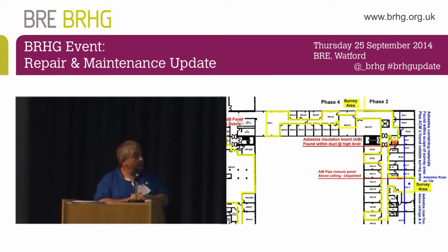And the requirement is, wherever you're doing building and maintenance works, that you do a refurb and demolition survey. That's much more intrusive than a management survey. And we have to make sure the client's aware of that, because they say, well, we're going to open up the ceilings. Well, hang on, Dave, they're all brand new ceilings. I said, well, do you need to go above them? Yeah. Well, then we're going to need to get into them. But as they're all brand new ceilings, what we do is we use cameras instead. There are ways of doing it without damaging the infrastructure of the building.